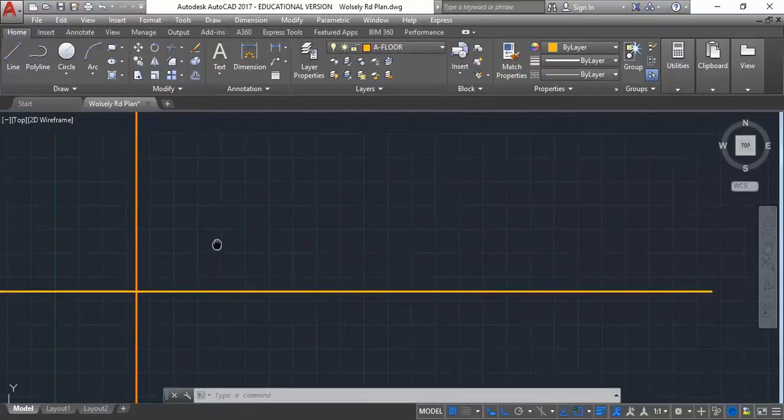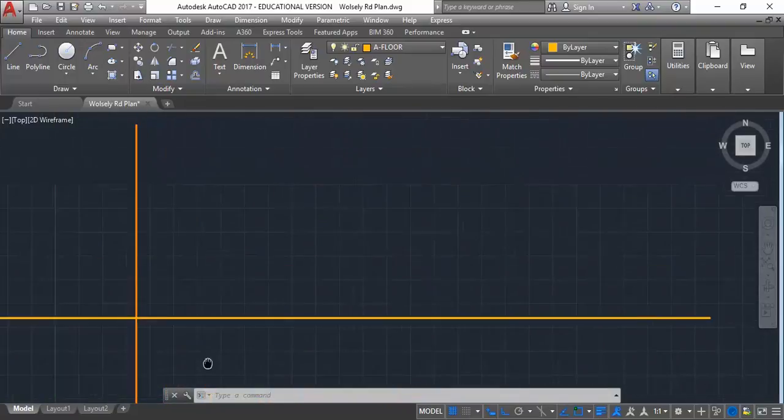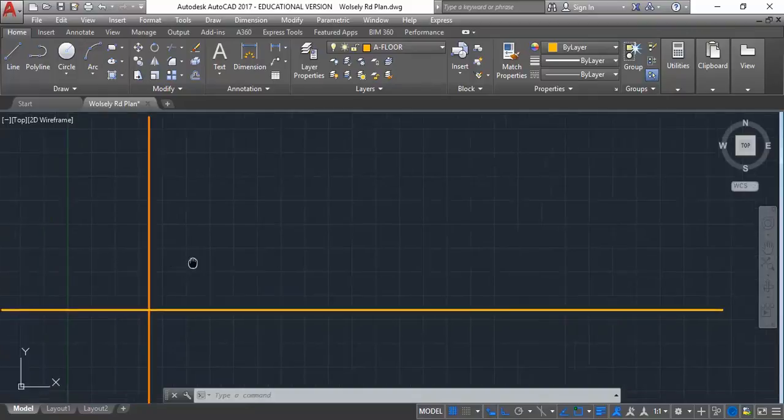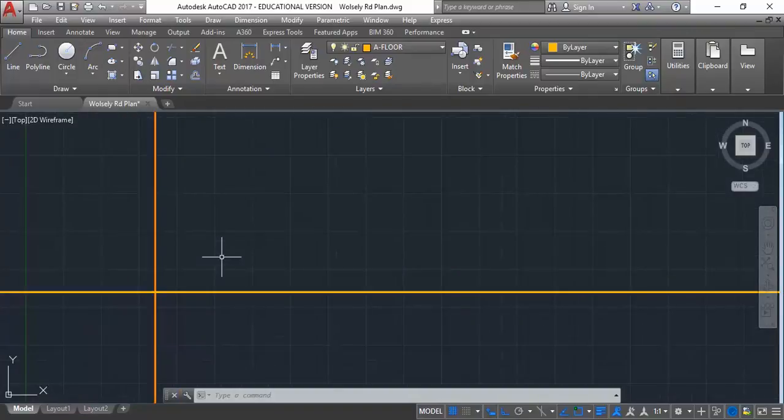Okay, so I've located the floor. Do you have an idea how thick the floor would be in a building like this? That'd be a thick one. Yeah, it could be up to that thick. For a building of this size, I'd say it's probably even less than that. So 200 at most, I'd say, would be the slab thickness. The ceiling might add more to it, but we can just do it 200 for now.